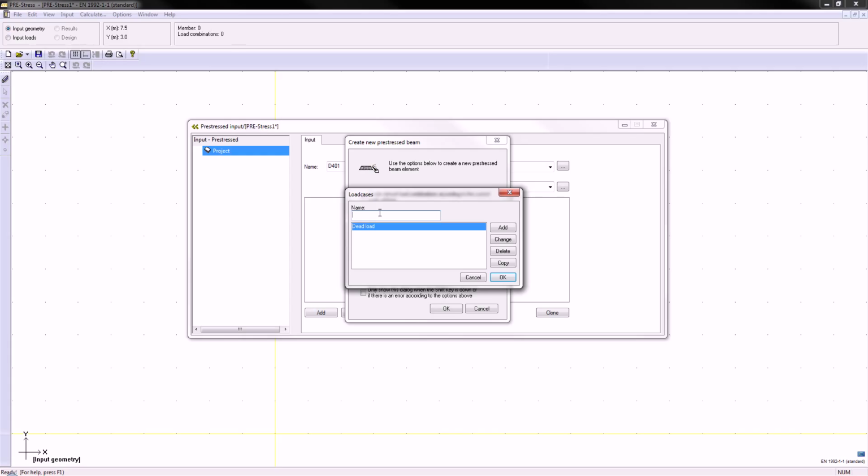I will have live load on the element, and it's also, as you can see, possible to add all the different kinds of load cases as you will be having in this example. So I will be adding a topping as well, and this topping is a non-structural topping, so it has no interaction between the element. It's only treated as a load.